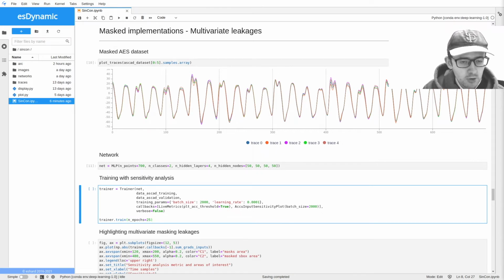Masking is a countermeasure where sensitive values, like the keys for example, are split into multiple shares that are manipulated separately. It protects the implementation against side-channel attacks because the sensitive value itself is never manipulated by the algorithm. The algorithm actually operates on the shares instead.